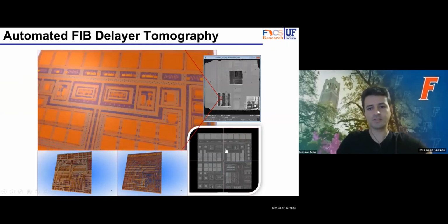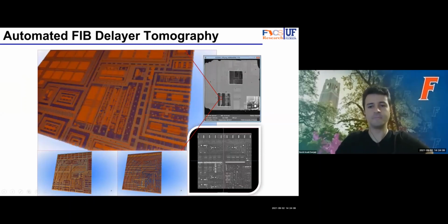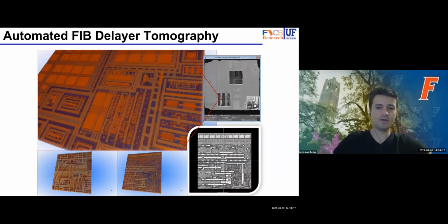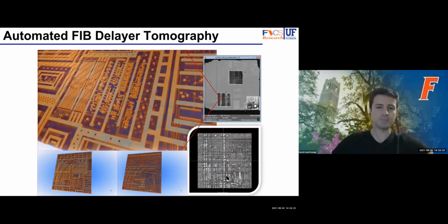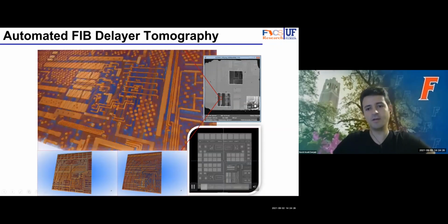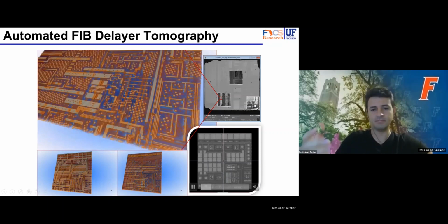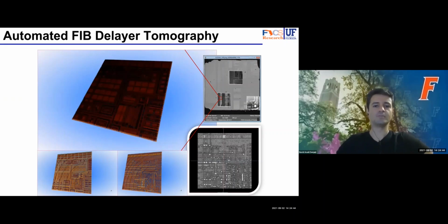So as the FIB-SEM imaging has been repeated in a loop, you see as we go to the middle, it starts from the doping, then to the poly, contacts, metal 1, 2, 3, all the way down. And as you go down, there are also some defects coming out. Those defects are because of the redeposition of the beam itself back onto the circuit. Sometimes the beam doesn't work as robustly as it should, which is very normal for these tools, and a lot of challenge there. So eventually we get to some of these images.